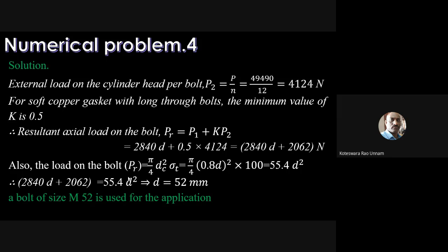Similarly, in the case of welded joints, we discussed two cases. In both load cases the first thing is the primary, direct shear stress. In one case you have a twisting, torsional shear stress, and in the other case you have a bending moment. If the load is in the plane of the joint, you have a twisting moment, or torsional shear stress, which we call the secondary shear stress.